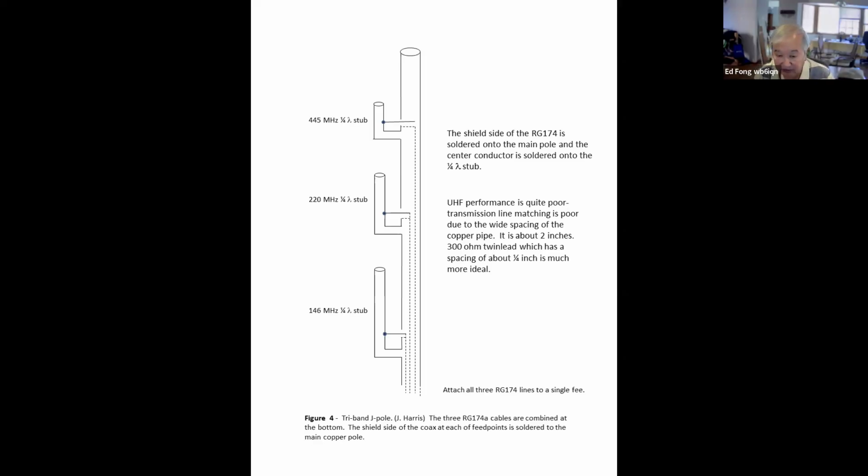That's the thing about antenna design, right? You can electromagnetically meet all the equations and the thing works. The second question is, is it practical? It's what a mathematician would say. You get one to resonate, it may be necessary, but is it sufficient to make a good antenna? Well, as you guys know, an antenna requires 2 things. It's got to be necessarily resonant, but then it's got to be practical. That's the other thing. Mechanically, can you make it? Is it feasible? It's not just the electromagnetic. So this is electromagnetically feasible, but it's pretty hard to make, at least at a good cheap price.